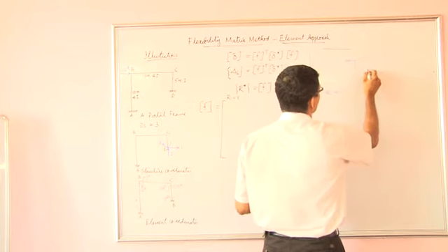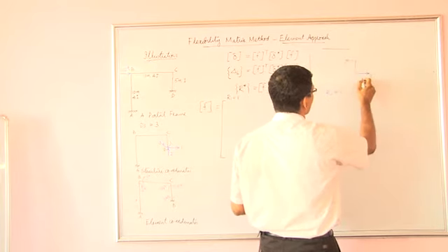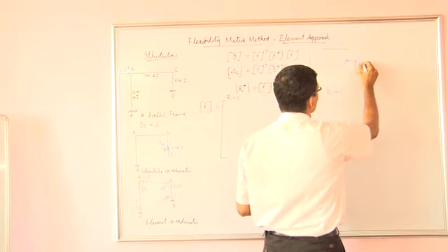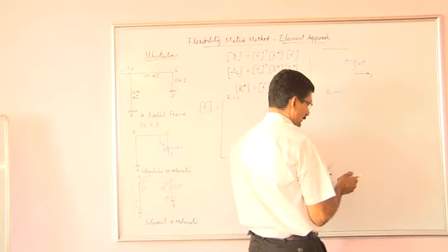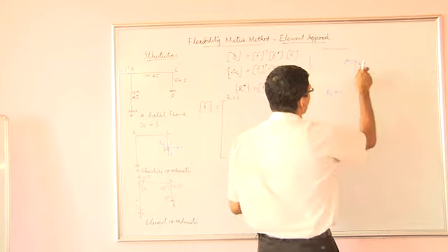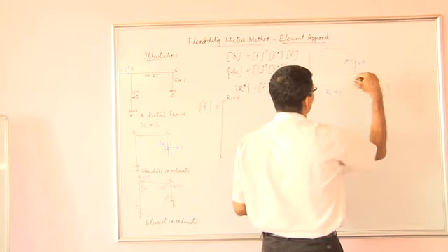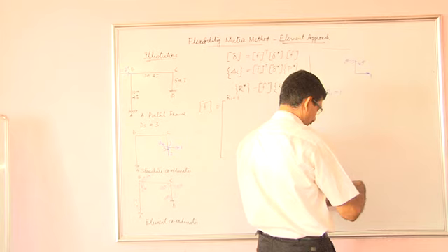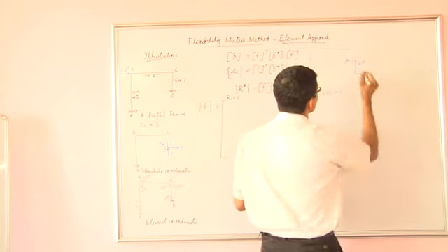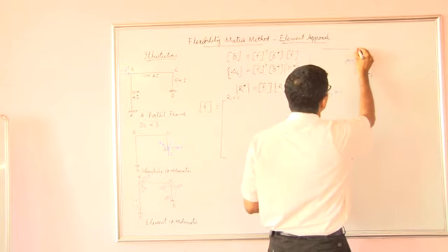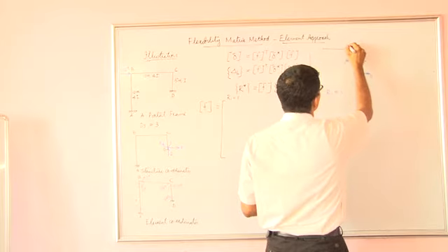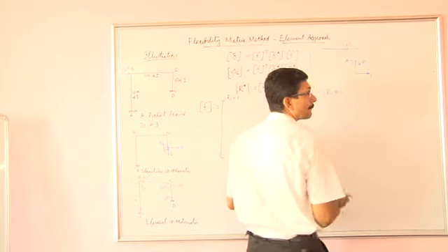The moment produced by these two forces will be 1 into 5 anti-clockwise, so you require a clockwise moment for equilibrium. This is 5. Further, we transfer these forces with their opposite signs to this joint in the beam. So this will be 1, and this moment anti-clockwise will be 5.